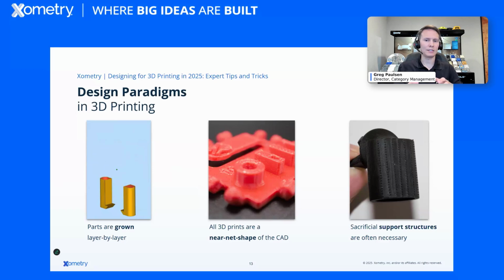The other side of this is that additive manufacturing machines are doing their darndest to make your 3D digital design, but you cannot stop them and tune a feature like you could in CNC machining. So for example, say a hole has a very tight tolerance, I can't stop the mill, go inside, measure, adjust my offsets, and then cut again and check it out.